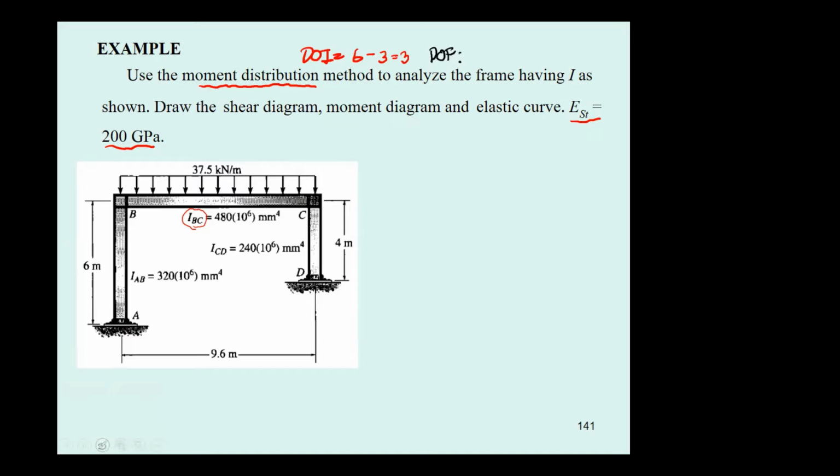If you consider the degree of freedom, you can consider how the structure deforms under the load. The stiffness of the column is based on EI over L. Since the L of this AB column is large, this column should have smaller stiffness than the column CD.